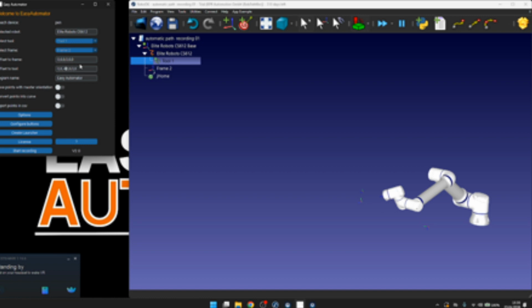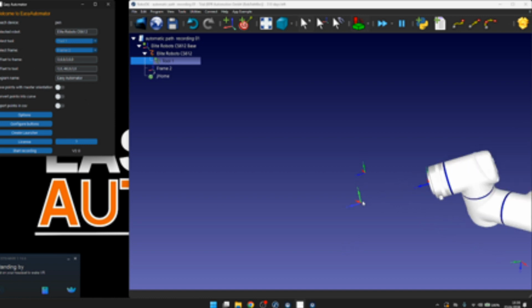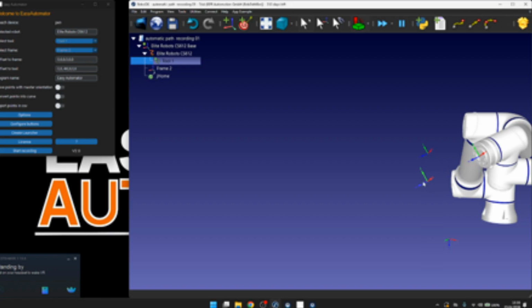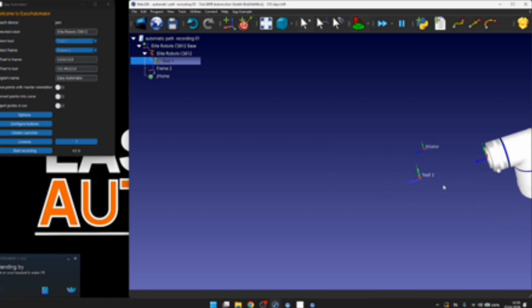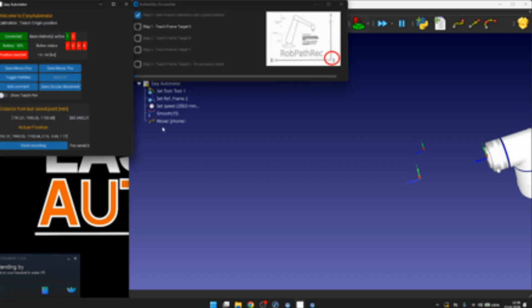If you have trouble with this, you can always check out the coordinate systems, and this is the tool TCP that we will use. Here you can see, okay, I want to move toward, along, or back in the direction of the robot. This is up to you. I was just defining only minus 80 millimeters. That means I will touch the screen, but in reality the robot will come 8 centimeters away from this surface.